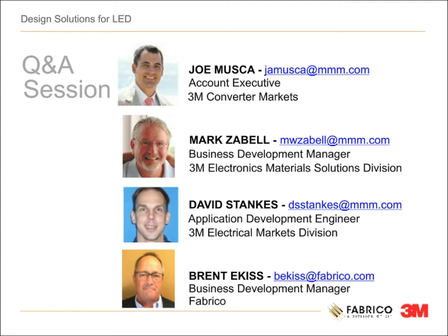Hey, this is Joe. I'll take that. From thermal interface pads, they've got a high dielectric strength, and so they do a very good job of isolating live current. But the silicone TIM dielectric strength is a little lower, and acrylic TIM constructions are higher. So the acrylic TIMs should be evaluated for the maximized insulation characteristics.